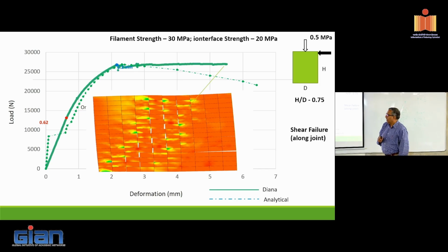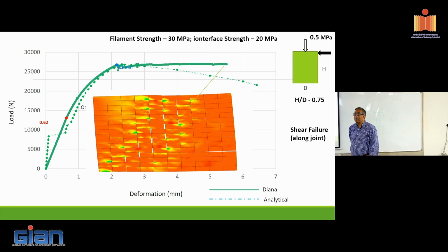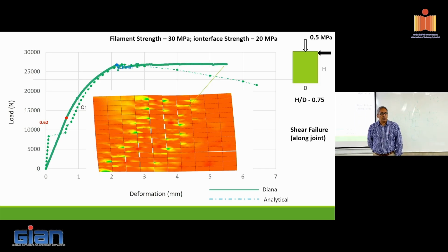Okay, so can we still use an engineer's judgment, take the weakest direction? Possibly, right? But then you always run the risk of not being able to identify shear induced failures. Okay, and a saner approach, something which is more systematic, would be something that we basically draw from our experience of masonry, brick or stone masonry. There are enough analysis programs that are available that you can analyze this at different levels of discretization. Whether you want to do a micro model, a meso model, all of those are available for masonry.